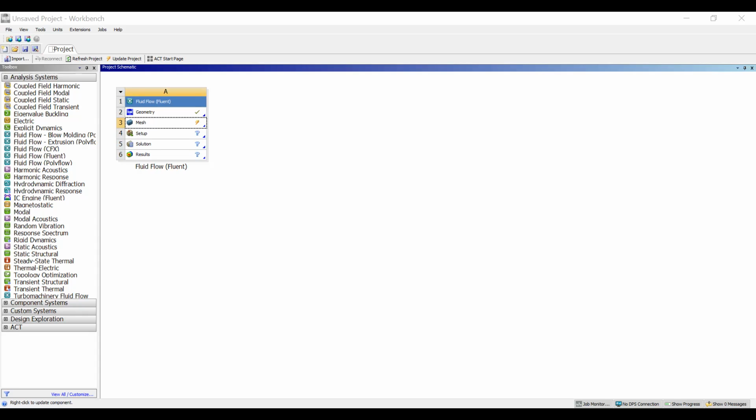So you can see our mesh is much more refined now, and especially right around the cylinder, you can't even see it, it's so dark. So you really zoom in. It's a nice, good definition of points. You can even check kind of the precision of your mesh by looking at your nodes and elements. Our statistics on there, so you can see very high. We want to keep these under 400,000. So we're good here. We should be able to get some good results, hopefully.